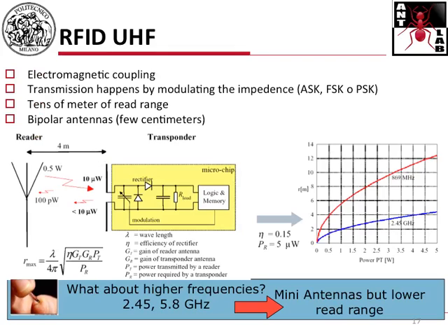In the electromagnetic coupling, as I was saying, we are more flexible in the range, in the sense that the range basically depends on how much power we are putting in the electromagnetic field. There are different laws which tell you what's the maximum range you can have, such that the generated current is enough for letting the tag work, and these laws depend on the frequency we are in.